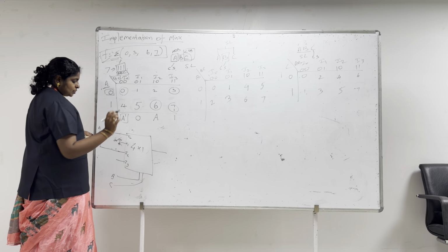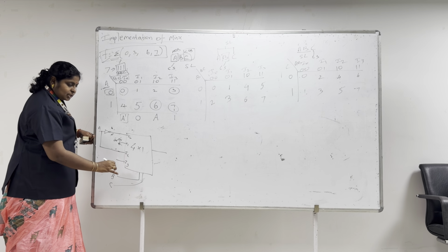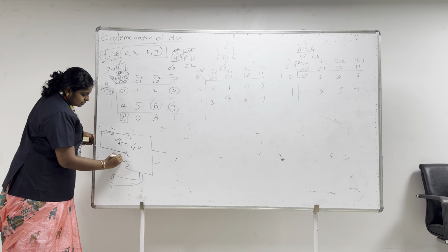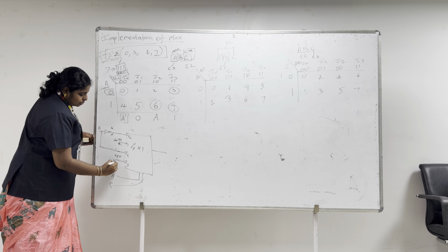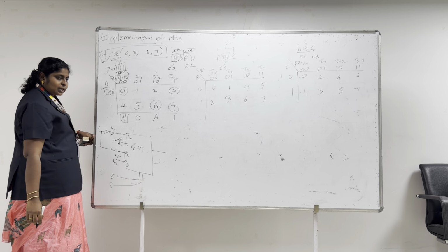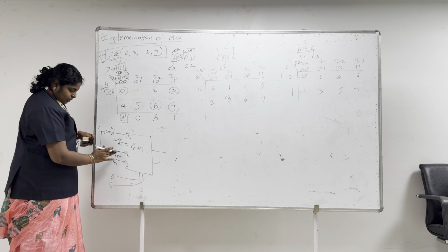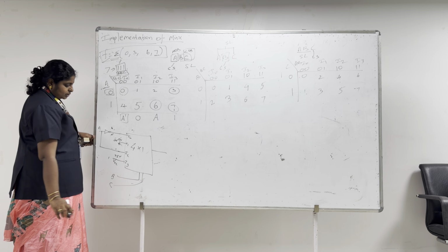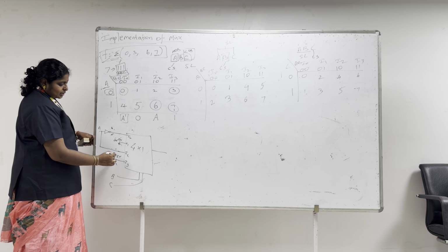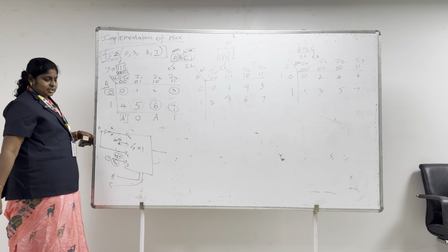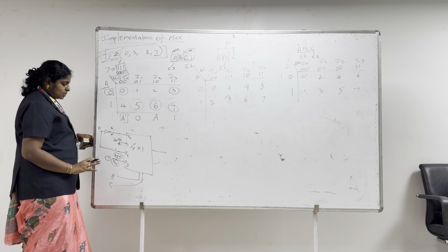I3 is 1, therefore it should constantly be given the input signal 1, so plus 5 volt, or else you can give it as VCC. If you are not getting into these concepts, just go with one and represent it as one. Any one is enough, not all three.